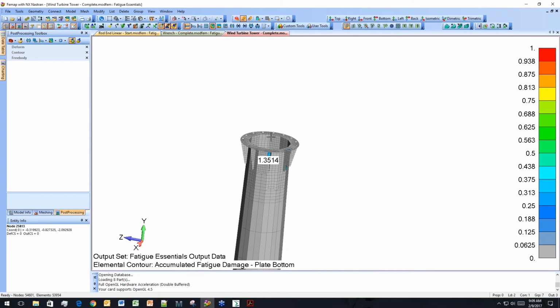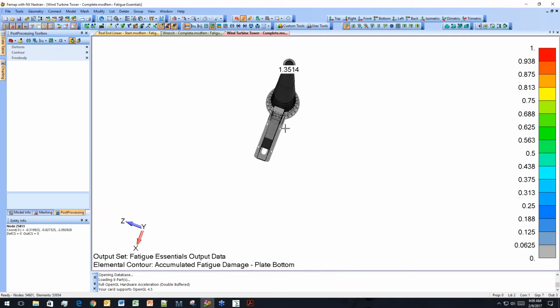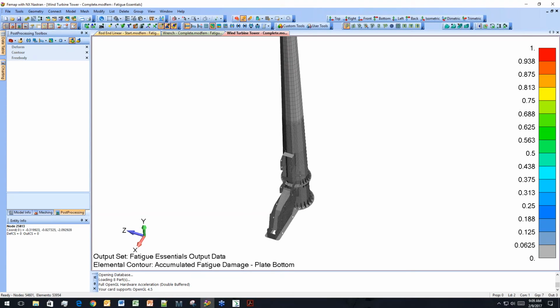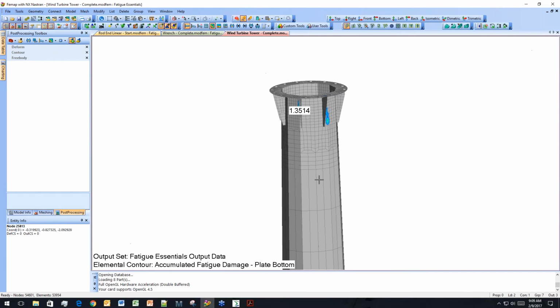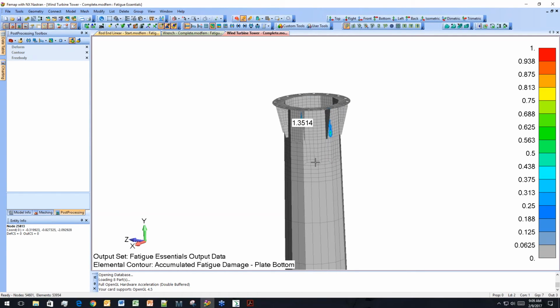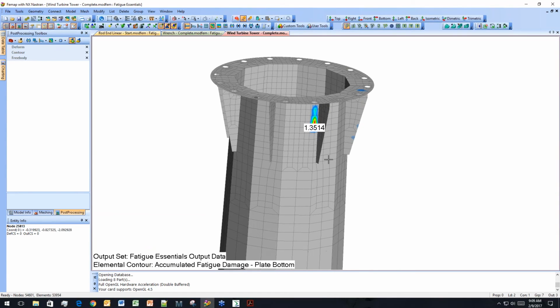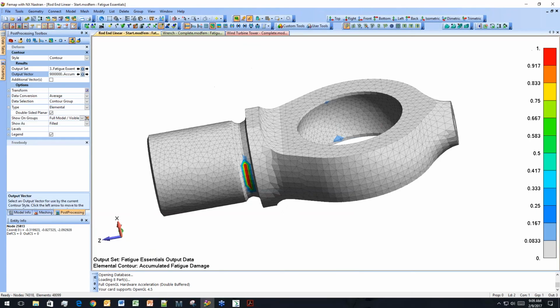This is why it's useful to have your GMap contour your fatigue stress, because you might pull out a couple different areas of stress levels as you're doing your hand crank fatigue damage. But this is really all-encompassing. It grabs all of your nodes that you select, and it'll calculate the fatigue damage for all of them. And then, as a bonus, you get a nice picture to put into your engineering reports. And who doesn't like pictures? So that's our FEMAP plugin.